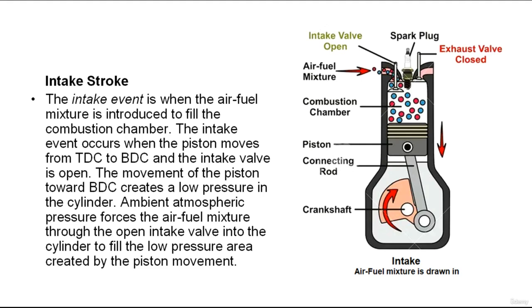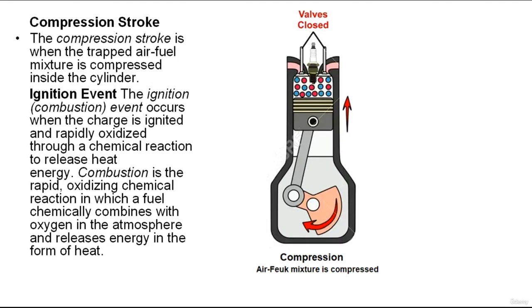It continues to enter the cylinder until the intake valve closes, and the intake valve closes after the piston has reached bottom dead center, or BDC. This delayed closing of the valve increases the volumetric efficiency of the cylinder by packing as much air and fuel into it as possible.